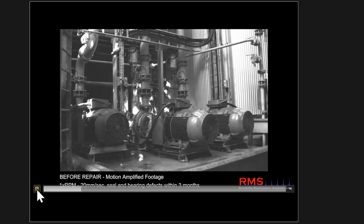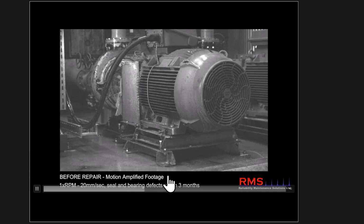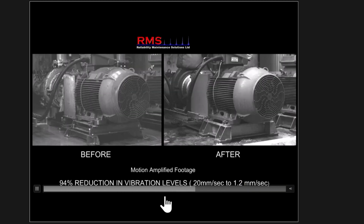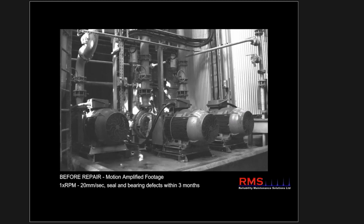And again, you can't see this with a visible eye, so it's ideal for bed plates and things, what you're looking at there, and how things are moving on the actual bolts. A lot of the time, bed plates are really poor, fixtures are bad, and people tend to forget this. So there's the before and after they've done the repairs. And we can then show that as a video rather than trends and vibration data.